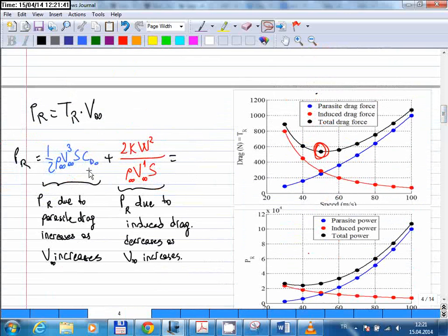And if you look at here, it depends on certain numbers. For example, it depends on the weight. If you change the weight of the aircraft, then these curves will change because you have weight in those equations. Or if you change the altitude, then air density will change and these curves will change as well, right? So you have different curves for different altitudes and different weight values. And I will be talking about the altitude dependence next. But we don't really have too much time left, so I don't really want to start that subject today.